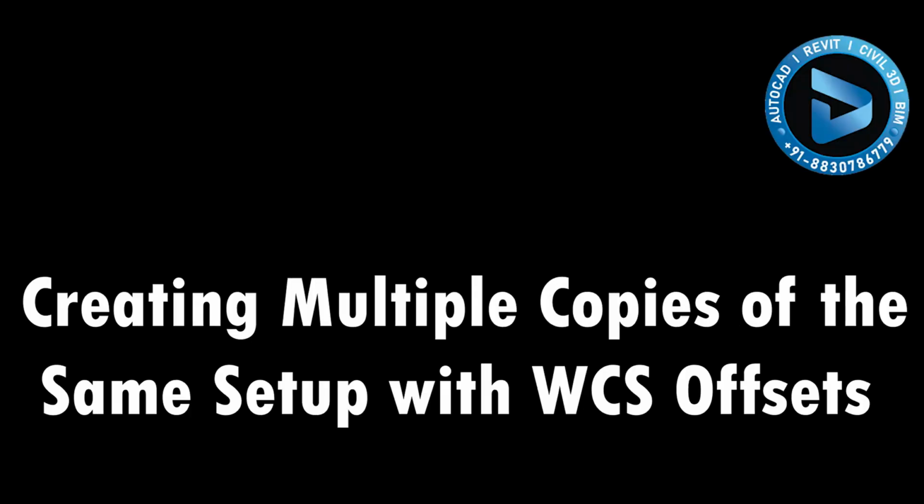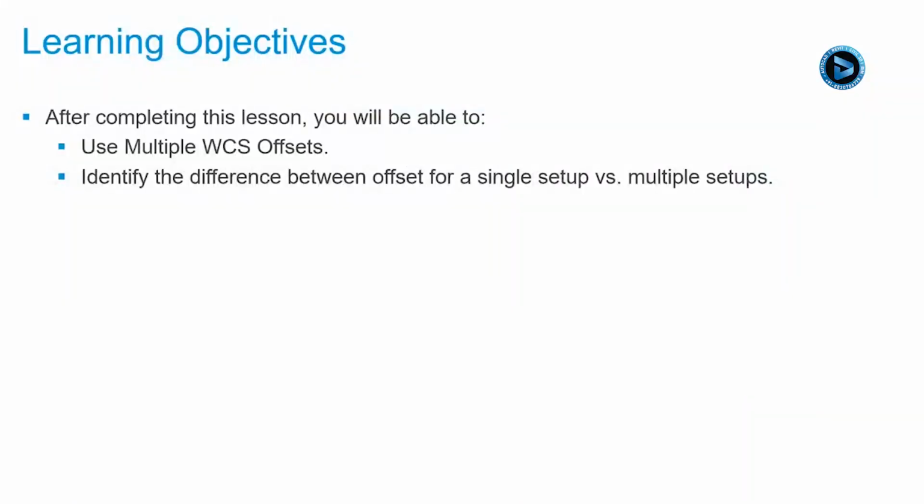In this lesson, we'll be creating multiple copies of the same setup with WCS offsets. After completing this lesson, you'll be able to use multiple WCS offsets and identify the difference between offset for a single setup versus multiple setups.